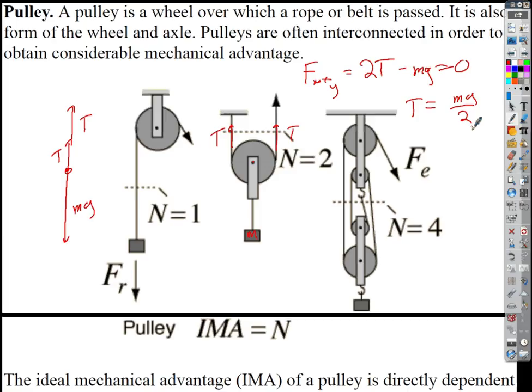That's good. So what's our mechanical advantage? 2, right? Because the output force is twice as big as the force we're applying. 2 times T equals mg, so mg is twice as big as the tension. Does that make sense? Using this setup, we can hoist this thing up using only half as much force as would be required to pick it up without the pulley system.